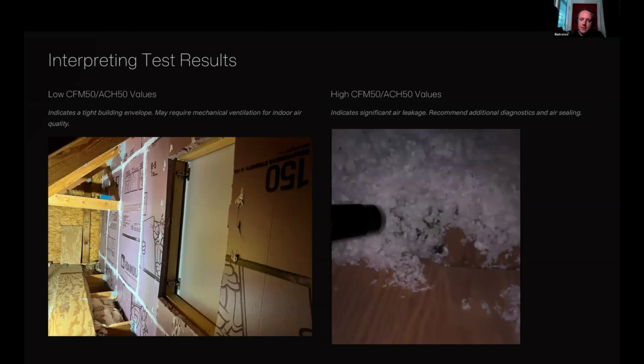Basically, the only exception to that rule is 24-hour continuous ventilation. Those are the systems that can be taped up. I doubt that's going to be running 24/7, so that's not going to count for that. So yeah, you really wouldn't be allowed to tape that off. That would just count as part of your blower door number.